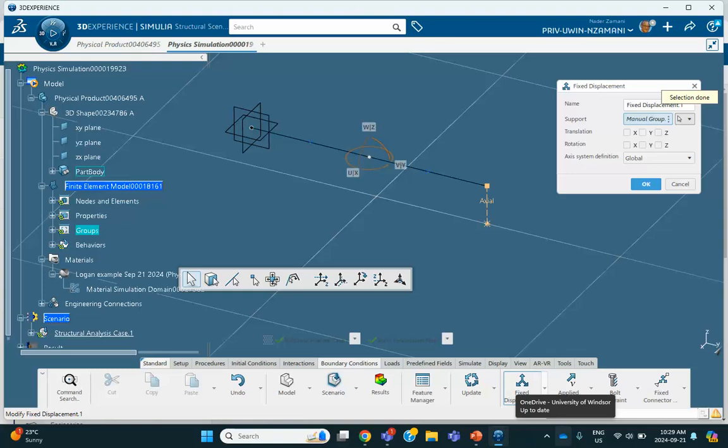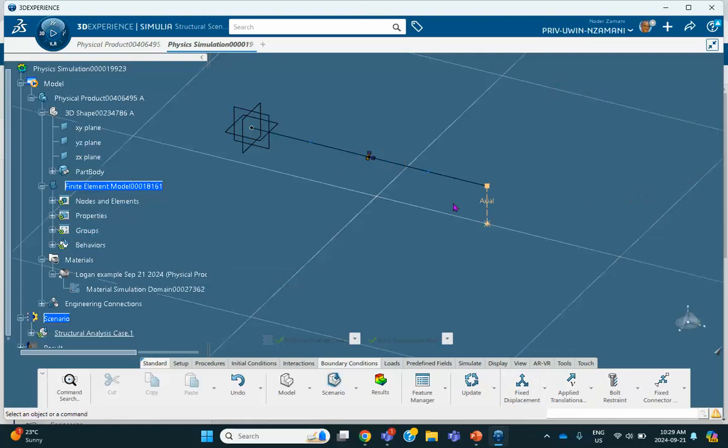Excuse me. Okay, this can slide in the y direction, so that's free. X and Z translation are checked. It can freely rotate about the x-axis, global x-axis, and these should be checked. So, okay, there we are. And that's pretty much it. Oh, load.